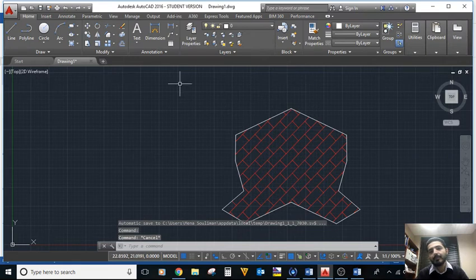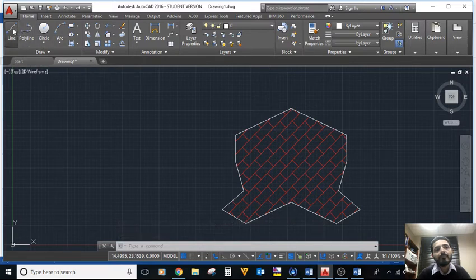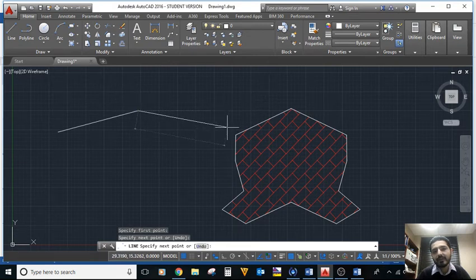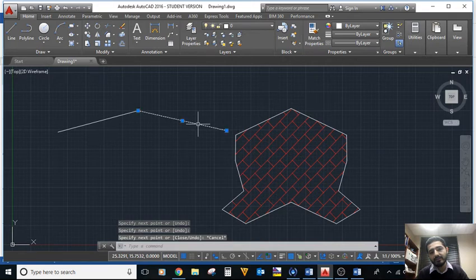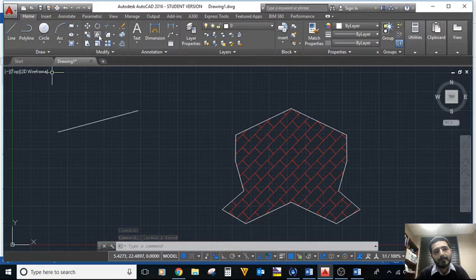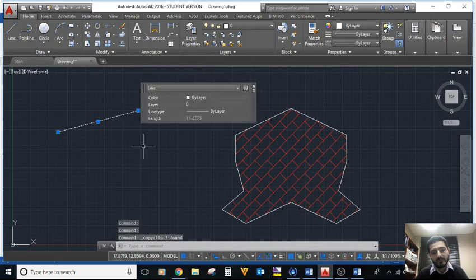So how can we do it again? Let's skip and do another drawing here. This drawing is a typical drawing for a cross section of the highway. Let's draw, and typically we design those highways with a crown, and let's actually use the mirror since we just learned about it. I'm gonna use this as the first line, and then I'm gonna copy this.